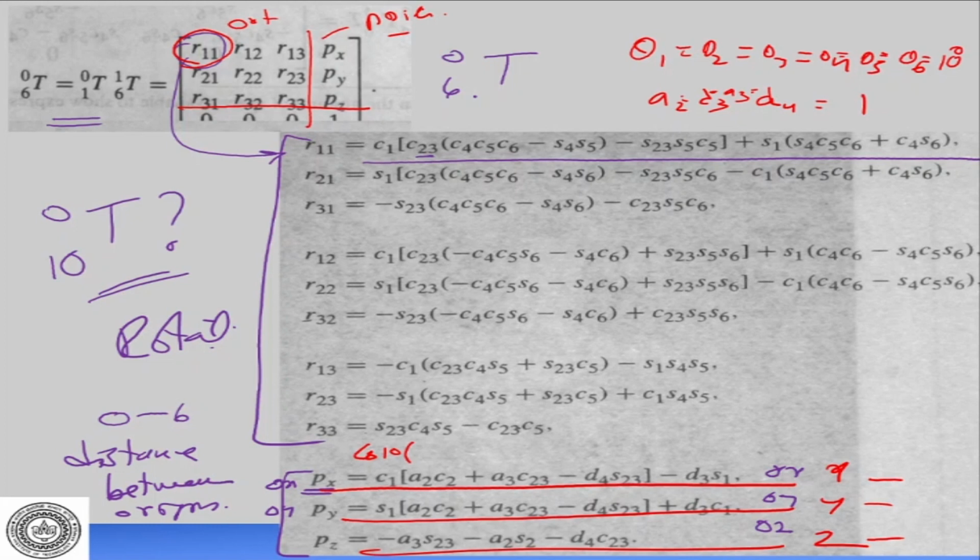So today we looked at the forward kinematics of robotic systems. We looked at the Puma robot, completing it as we started in the last class. Then we looked at the forward kinematics of a 3 degree of freedom planar manipulator, and we saw that there are 3 equations and 3 unknowns, so we can solve. However, keep in mind that your thetas come in all combinations, multiplications and additions, like theta 1 plus theta 2 in that order, so it is not always guaranteed that you can solve. There are manipulators which do not have solutions. For example, the human arm does not have a closed form solution.